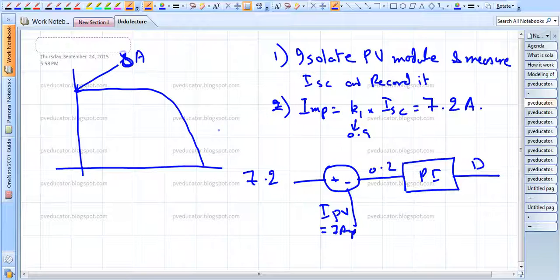It is because of two reasons. First, there is no intelligence in this method. In the conventional short circuit current method, there is no intelligence at all, so it cannot detect the change in weather. For example, if your panel is operating at this new photovoltaic power and voltage curve, it will never be able to know that this value has changed.